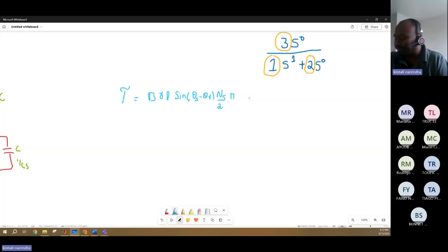You have seen the derivation of this equation. Now, if you observe this equation from a mathematical point of view, there is a sine function included in this torque equation, sine of theta s minus theta r, the angle of the stator minus the angle of the rotor.